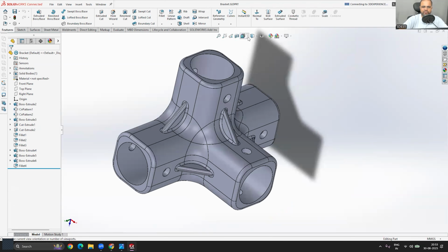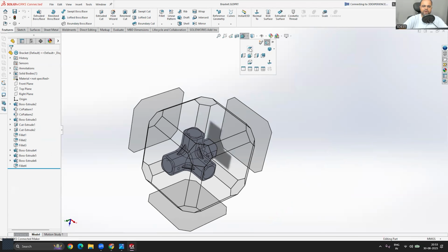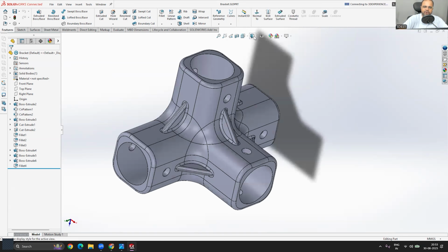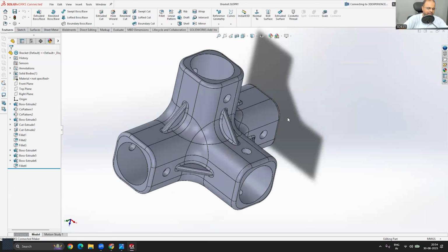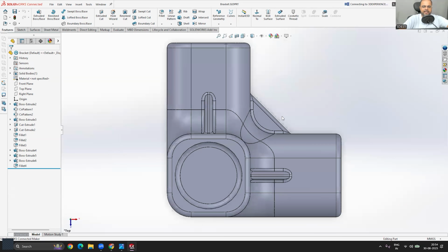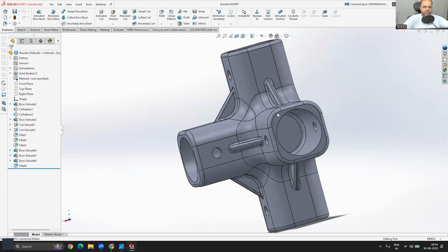Next to the section view, we have different views available over here, for example top view, left view, front view, side view. For all these views, we also have shortcuts. If you move your cursor onto the tool and stay there for a few seconds, a small window will pop up where you can read the information with the keyboard shortcut. If you want to go to the top view, you have to press Ctrl+5, right? For another view like this one, Ctrl+3. If you press Ctrl+5, here you can see I'm going to a different view. If I press Ctrl+2, I'm going to a different view.